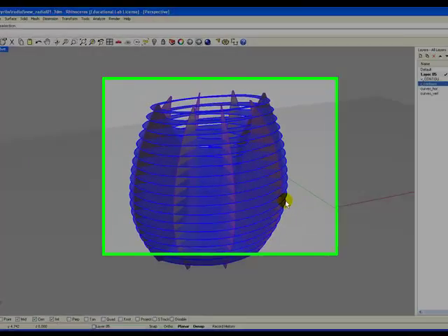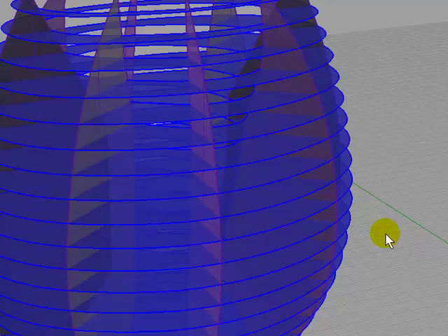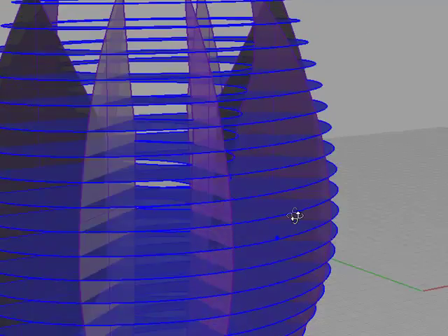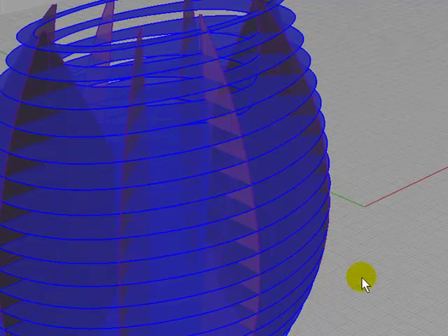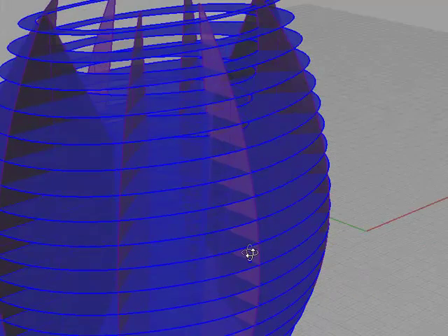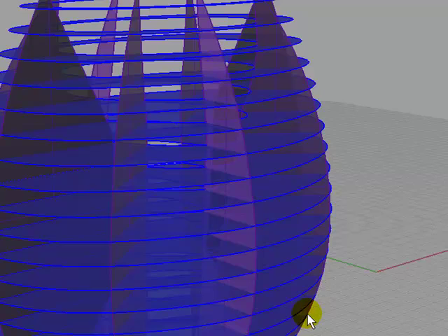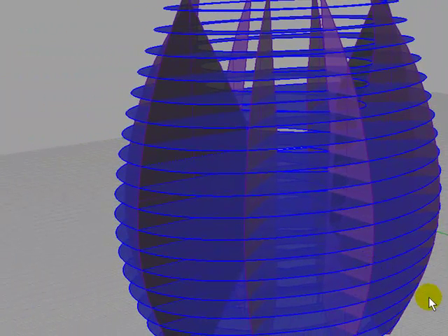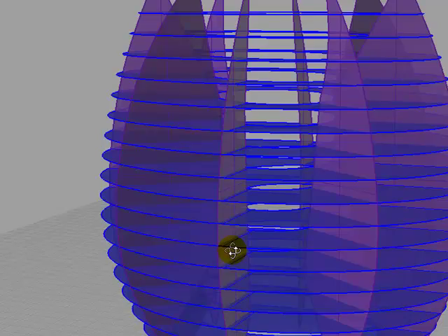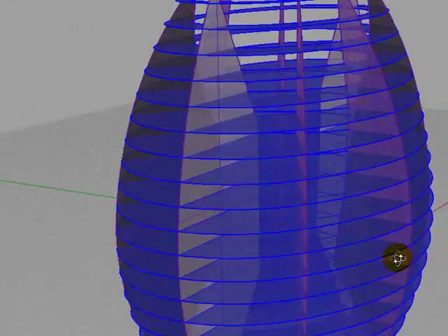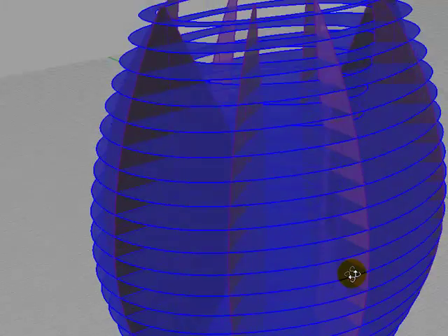Okay, now the final step in this part of the preparation will be to generate my intersection curves, because my intersection curves are going to be used to drive my piping operations, which I'll use to create my intersections for my ribs. But this is the basic model that I'll be using, and this is what my final object will look like with its thickness.